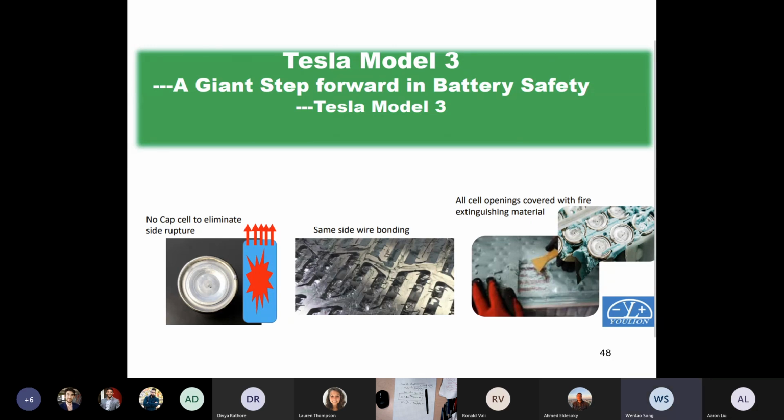So for the LFP cells, they don't have the so-called autocatalytic nature. They're more like first order kinetics. LFP really is almost inert relative to electrolyte. So the positive electrode side in LFP virtually does not react with electrolyte at all. So in an LFP cell, all the self-heating is coming from the reaction between the negative and the electrolyte. I see. Thank you.